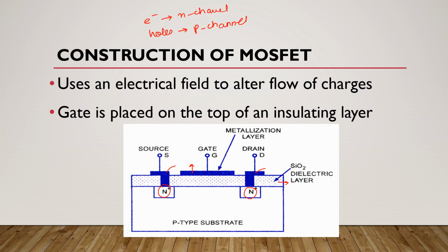We know that the gate of a junction field effect transistor must be biased in such a way as to reverse bias the p-n junction, but in case of MOSFET device, there is no such limitation. It means in MOSFETs, it is possible to bias the gate in either polarity, positive or negative.